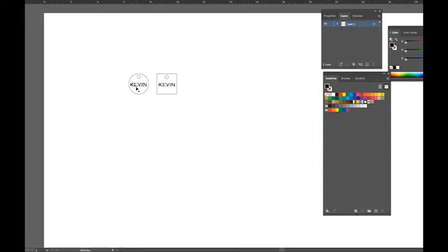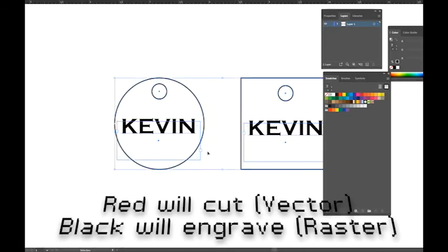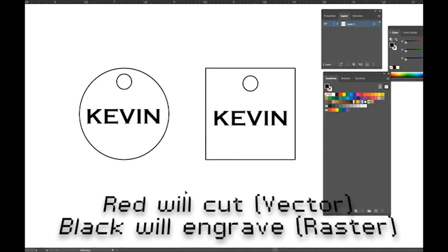The laser cutter operates on 2 specific colors that you have to set up at least the first time, and then once you do that, they'll be part of your library for the Adobe Creative Cloud, and you don't have to recreate them every time. So I'm going to zoom in here to my design, and I'm going to hit Control plus to kind of zoom in with what I have selected, move it around a little bit.